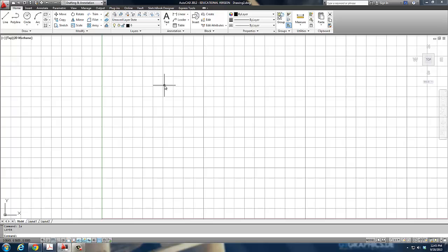Now, one last thing before I go. We're going to show you how to print and plot in just a second. I'm going to pull up a random drawing, show you how to open and print and plot it. But you'll notice one thing as we draw, all of our layers, everything we do, our line types, our line thicknesses, our line colors, are always controlled by layer.